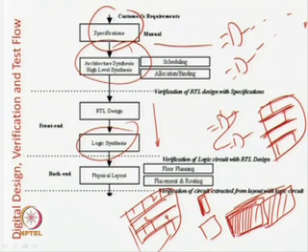This one we want to keep fixed, because the width of each row in the die remains the same, so that you can place them accordingly. And then, because different width, different length gates are there, you have to find out how you can place these blocks here so that the maximum number of blocks can be fitted, or you take minimum area. So, again, it is a very interesting computational problem, how to do that.